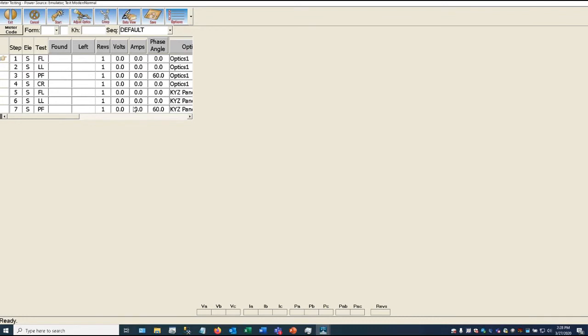And then same thing with all of that selected, I can then choose what test sequence I want to run, and then with that generate the same harmonic content that I just saw at the site several minutes ago. Overall, this is how to generate ANSI waveforms, harmonic content, whether custom or seen in the field with an RW, and how to apply those to meter tests in the RW and Bantam Plus.